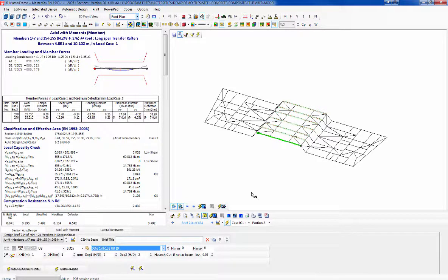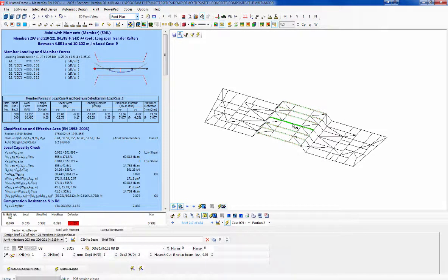So if I was to come along, so 203 102 it says is the lightest. It thinks that's okay, the 178, but when I move into an inner beam, it's also using that 178, and one of these, this one, is not happy. So it's done all 8 beams to satisfy all the design checks together, and it's found that this baby is not happy under deflection.